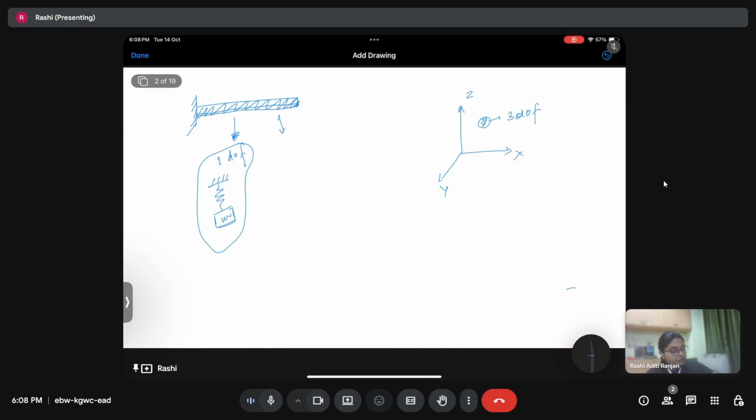So what we can do is model it as an n degree of freedom system, which is going to have n natural frequencies, n omega n's. But then again, this is not exactly portraying how the system is behaving. So the option left with us is that we model it as a continuous system itself.